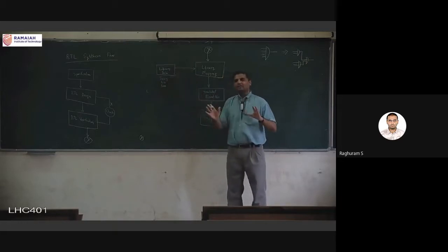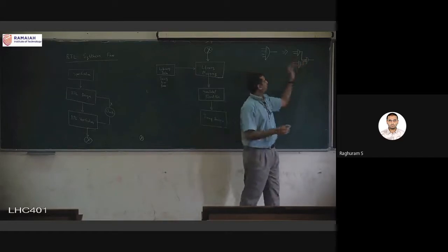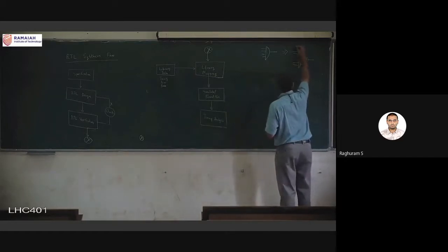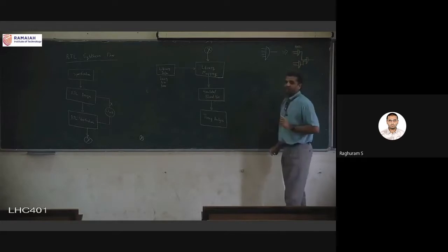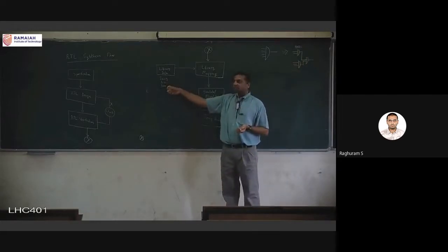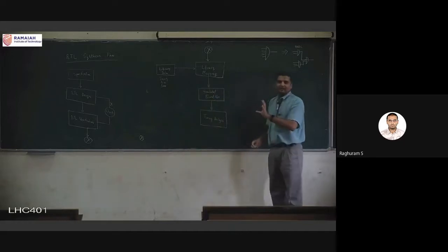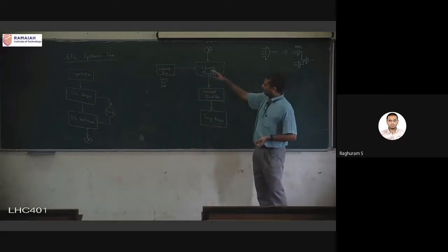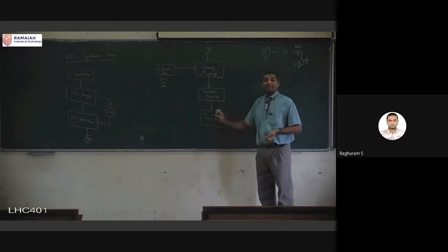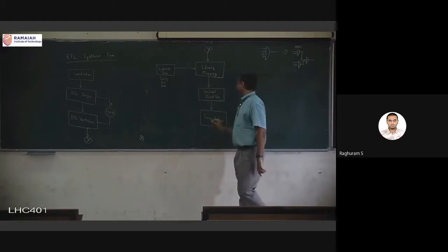Library data is nothing but a text file. It will have the name of the gate. So for example, this might be AND2. It will have the area of the cell, the timing information, and the power information, and this is all written inside a text file, and that is the library data. And once we have the library mapping and this, we can do a timing analysis for the first time. And again, if it is not satisfied, we have to go back.